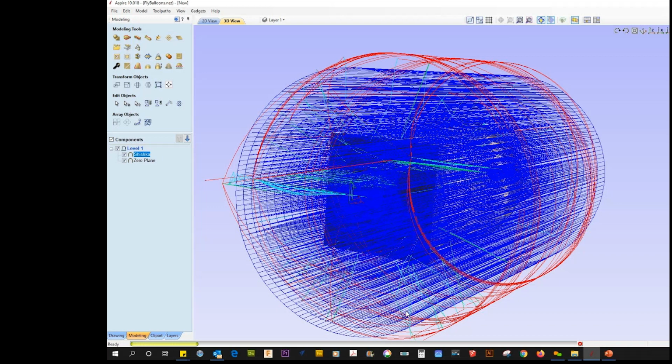I also want to mention, in Aspire, I found that raster is a better toolpath strategy than doing an offset. What I have noticed when you do an offset in Aspire is that the Z has the tendency of raising every 180 degrees.